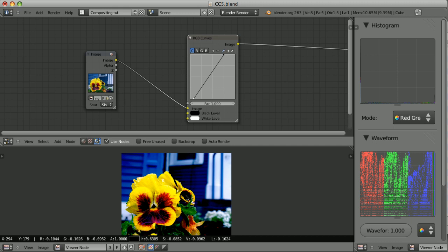So it may seem that it doesn't matter, but it does, because it's not that obvious that we will not want to change this image a little bit further by applying some other effects afterwards. Then here, those negative values will be taken into account. And in many cases it's not good. Here we see that blue channel exceeded 1, so it will be displayed as 1. But as well, if we do anything more with this image, this greater than 1 value will be calculated. Sometimes it's good to have the values greater than 1, but in most cases, negative values are nothing good. So we would definitely want to clamp this.